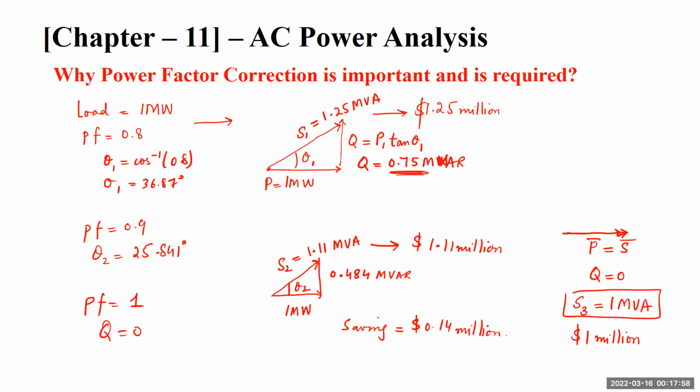The power factor decreases to 0.7, 0.6, 0.75, and in order to improve that, we use these capacitors or some other devices like synchronous condensers in order to improve that power factor, so that we are able to save the size of generator that we need in order to supply this power.